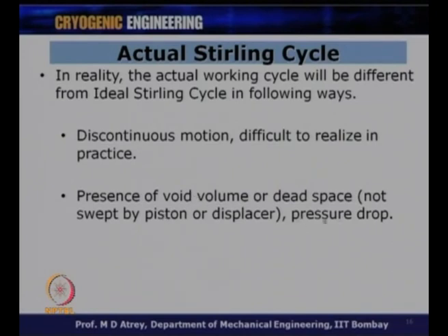Also, we will have pressure drop because the gas is traveling through regenerator, and therefore, gas will realize some resistance to the motion of the gas depending on its viscosity, depending on the porosity of the regenerator, etc. All right. So, in the actual Stirling cycle, we will have some pressure drop that also is taking the cycle away from the ideal Stirling cycle.